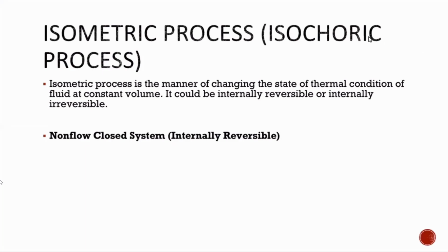Okay, so the first process is the isometric, or the other term is isochoric process. Do not get confused with the two terms. They are identical. When we say isometric process, it is the manner of changing the state of thermal condition of fluid at constant volume. So the keyword is constant volume. So it could be internally reversible or internally irreversible.